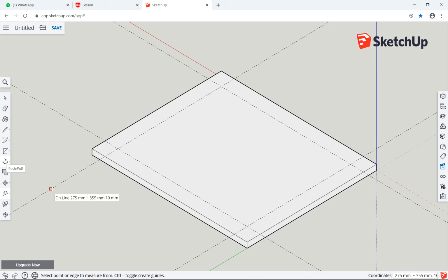Now for holes, I need to know where's the center. So let's say I'm using a diameter of, okay, for holes I need to create a circle, right? So I click here. So this is my first circle. So maybe my diameter of 5. So I put 5, but it's radius, right? So 5 divided by 2 is 2.5.